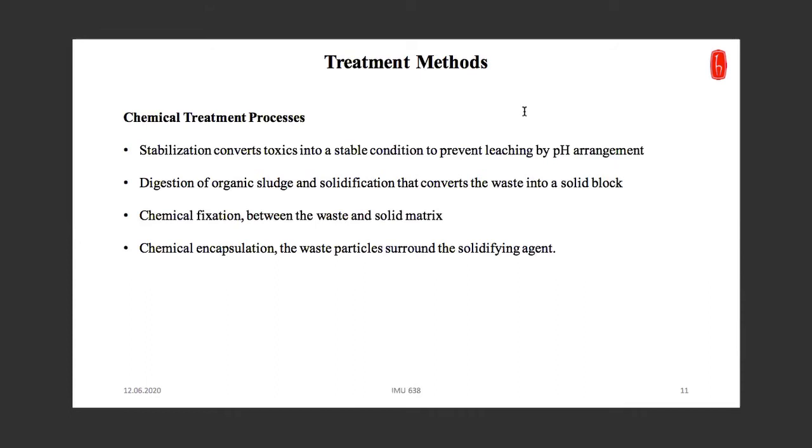On the other hand, there is solidification that converts the waste into a solid block by chemical fixation. I will explain this later. It's basically a bonding between the waste and the solid matrix, and also chemical encapsulation, which is the waste particles surrounded by the solidification agent. It's similar to the biological one, but chemical. It's just the chemical version of that.